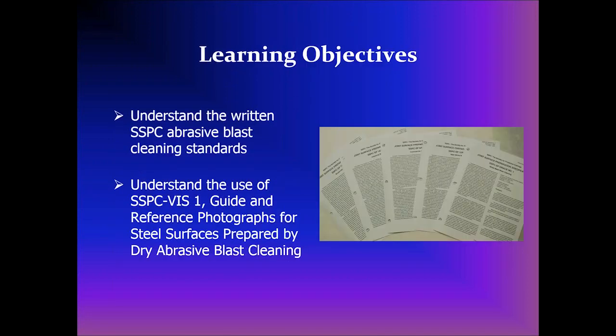The learning objectives are to understand the SSPC written blast cleaning standards and understand the use of SSPC-VIS 1, the reference guide of photographs that show you the different appearances of the various grades of blast cleaning.